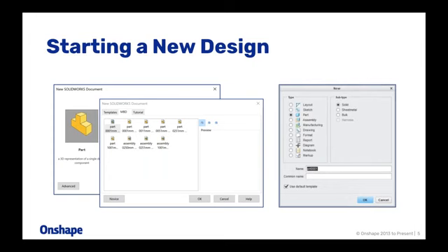And then it's a little bit more complicated when you come into Creo. So when you're creating a brand new file, essentially, it's going to give you the option: are you creating a layout, a sketch, a part, an assembly? Are you doing manufacturing? Are you doing drawings? Are you doing solid? Are you doing sheet metal? So there are a bunch of items that you have to define up front in order to be able to define the geometry that you want to create.